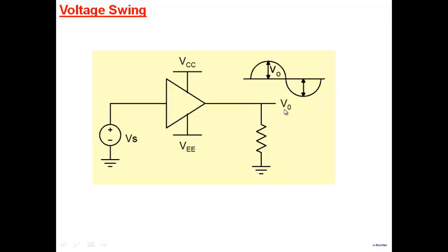And so as I said, you would like to build up V naught as high as possible, and of course the limits are that we would like V naught to reach as close as possible to the positive supply rail here, VCC, and similarly on the negative side, we would like V naught to reach as low as the negative power supply rail here. So when swing is of interest, we usually want what we call a rail-to-rail output voltage swing. Rail means this is the positive supply rail and this is the negative supply rail, and we want V naught to get as close as possible to VCC and similarly as close as possible to VE here. Okay, so we want that, but voltage swing is not always important.